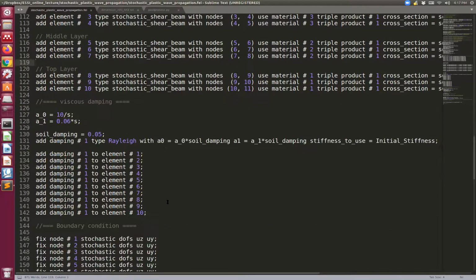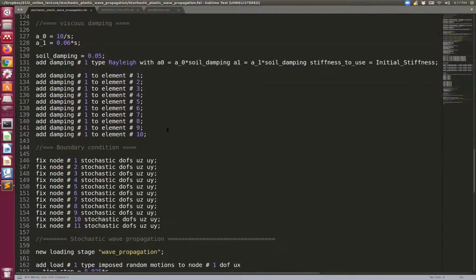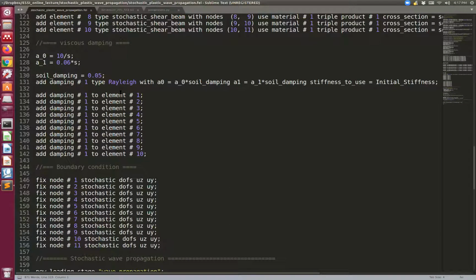And then obviously you can also apply the damping. So now the damping actually becomes a stochastic Rayleigh damping. This is the same idea. Essentially now the parameters alpha and beta will apply to the stochastic expanded mass and stiffness matrix.